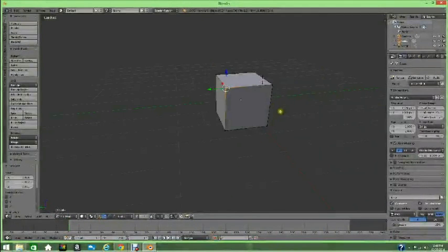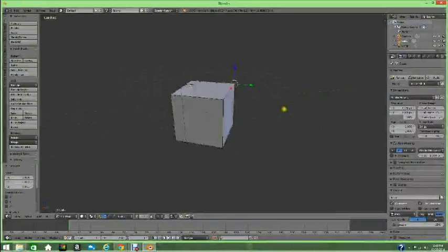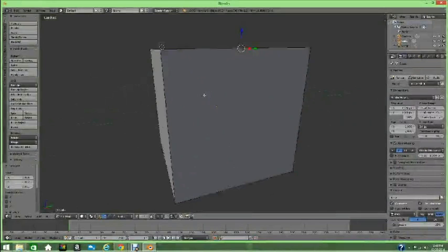The first thing you'll need to do to move around in Blender is learning navigation. In order to pan, you will need to hold the Shift button down while holding the center mouse button. This will allow you to pan around your view. In order to orbit, all you will need to do is hold down the center mouse button. If you would like to zoom in and out, scroll in and out with your center mouse button.